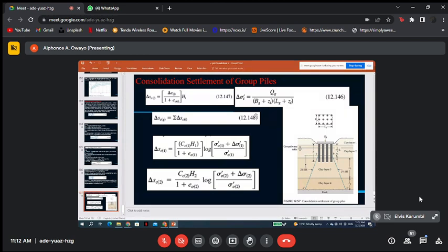But this is something you already talked about, the consolidation settlement. So this is nothing new, except we've added the dimension of the pile. Even from the idea of shallow foundations, you get it, because shallow foundations always have a dimension like that, and there's a formula for how to get the increment in stress at a point inside the soil due to some additional stresses. This is something you should have covered. There are certain formulas for doing this. If you add a load on the surface, then that load...